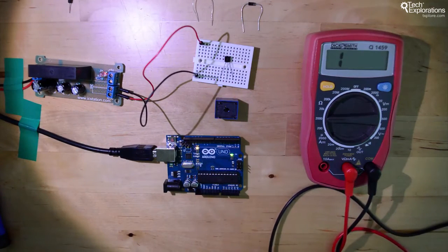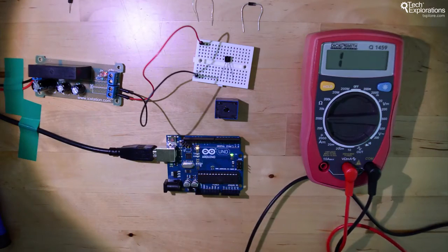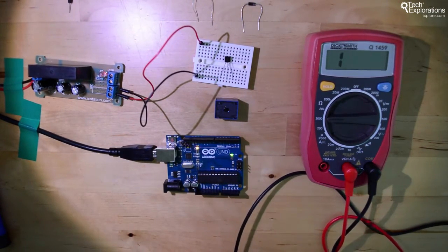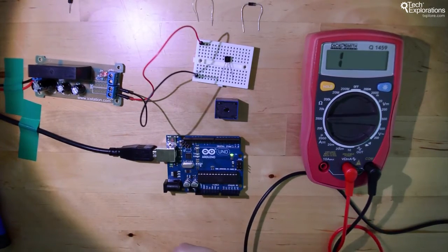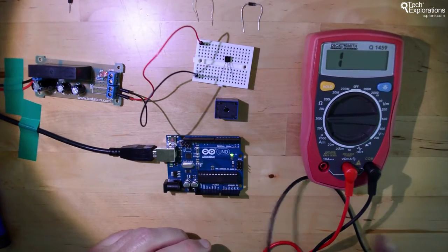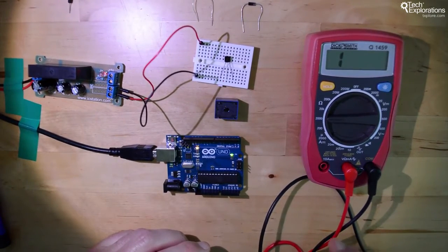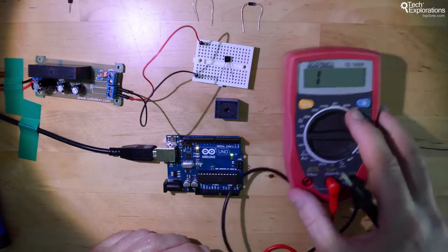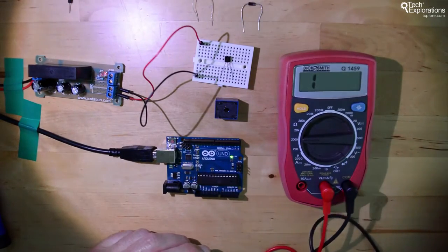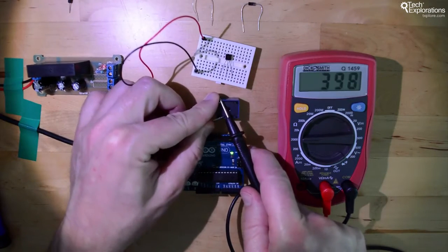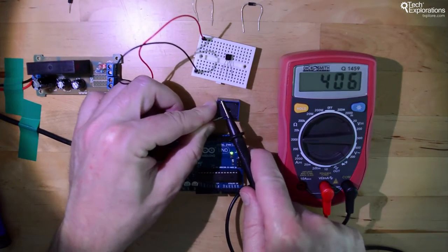The first thing we need to do is to calculate how much current we need in order to energize the coil. And just like in the first demo, what we need to do in order to figure that out is to first measure the resistance of the coil, and from that use Ohm's law to calculate the amount of current that we need to flow through it. So I've got my multimeter. It's set for resistance measurement. So let's check out how much resistance we have in the coil.